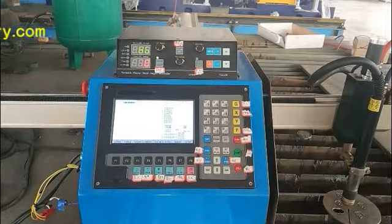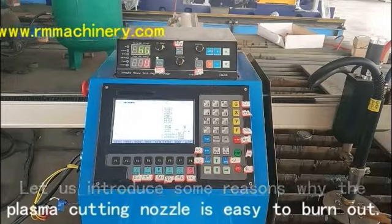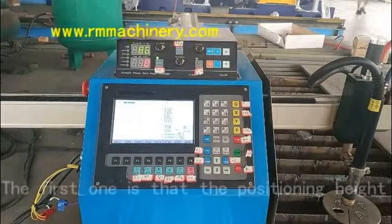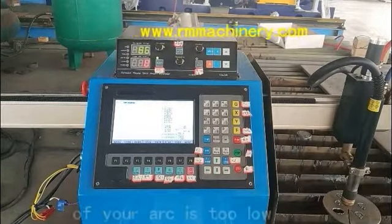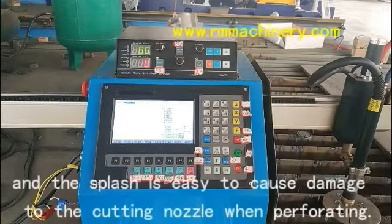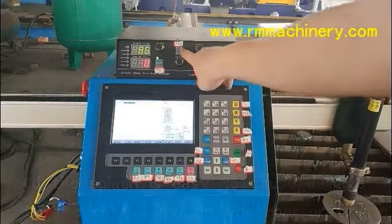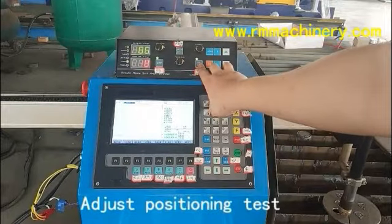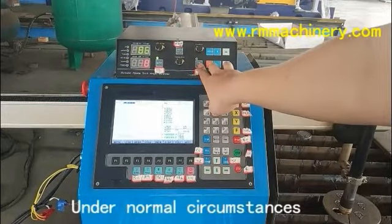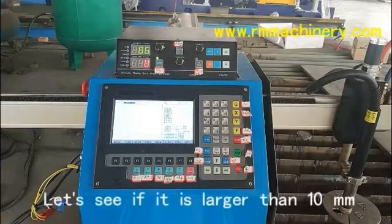Let us introduce some reasons why the plasma cutting nozzle is easy to burn out. The first one is that the positioning height of your arc is too low, and the splash is easy to cause damage to the cutting nozzle when perforating. Let's try this height. Adjust positioning test. Under normal circumstances, we recommend that the customer position the height at 10 mm to prevent splashing.